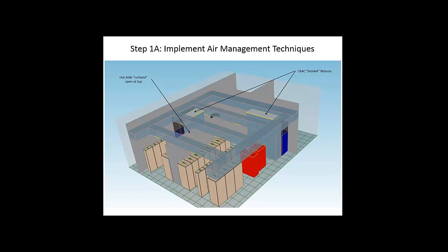So what I tend to do is I turn the RTI up, specifically the incoming flow rate down of the air handlers, until I start to see some RCI high problems, and then I look for opportunity to improve air management. And in this model I did two things. One is I put these snorkels onto the cooling units. A snorkel is the idea of putting a duct up into the air where the hot air is. The hot air naturally floats to the top of this room, and I want to go get it before it cools off. So these are just ducts. This is sheet metal. It's not very expensive. And you put these on the front, and it pulls the hot air down from up on top.